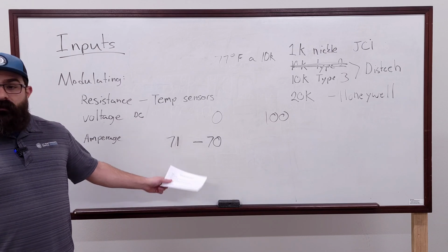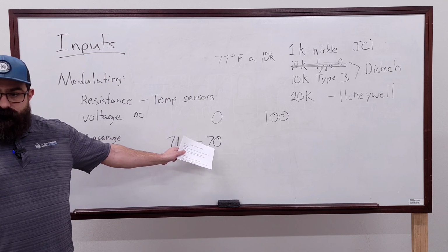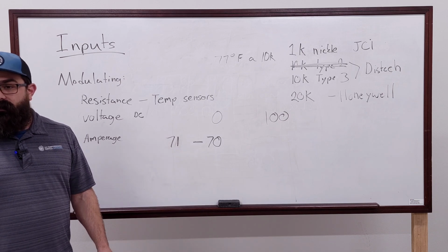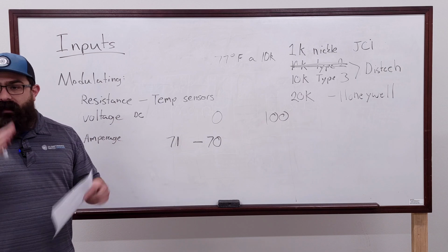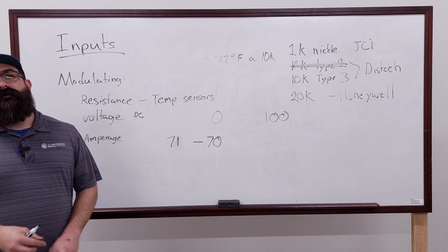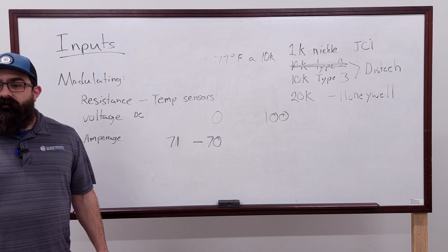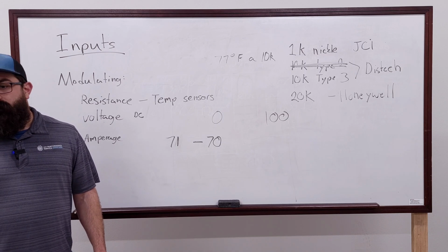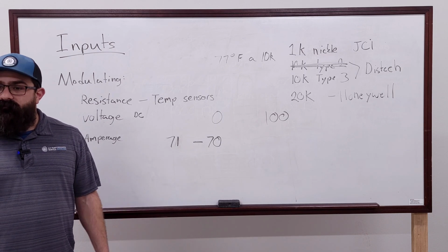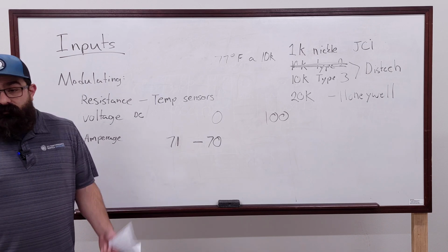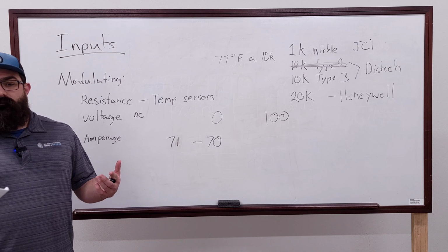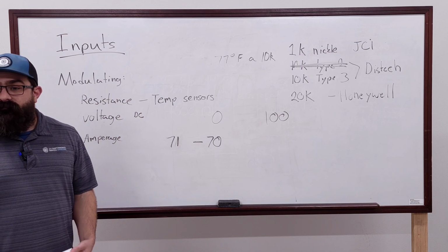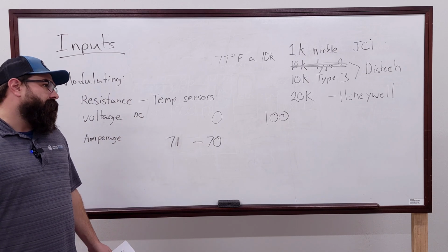You will chase yourself. If you start calibrating this to match that, as the temperature goes up, that's going to change, and then you're right back to having to calibrate it again. You're going to end up just back and forth. We struggle with that with some building engineers, because they'll walk around with their little thermometer stick and set it on a thermostat, and it says 72, and the system reads 74. And they're like, well, the sensor's bad. No, it's 3%. It's within the range. We can calibrate it, but come summer, when it gets 76 in here, it may be 2 degrees off the other way. I can't guarantee it.